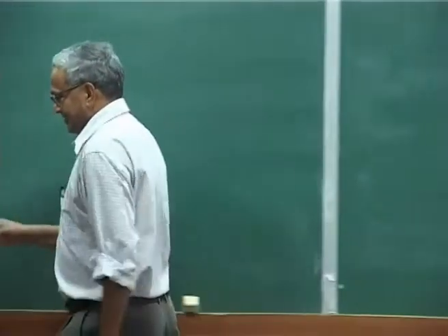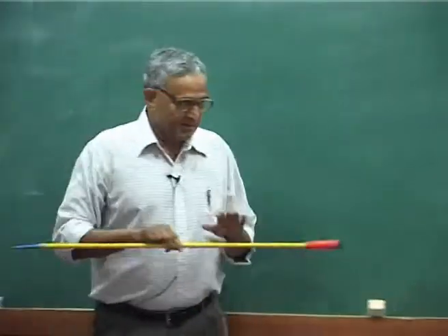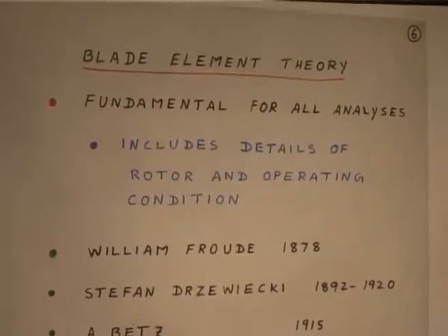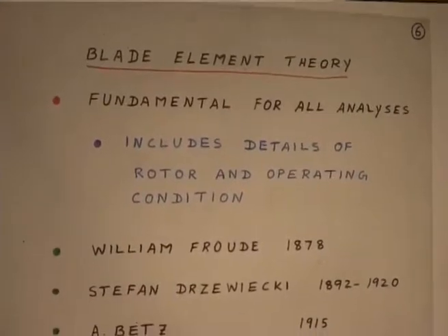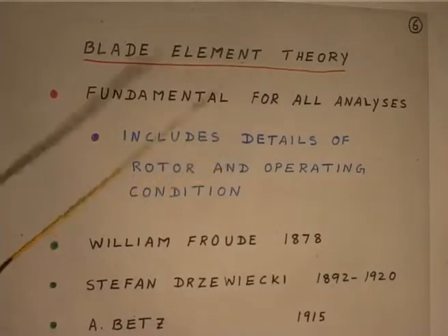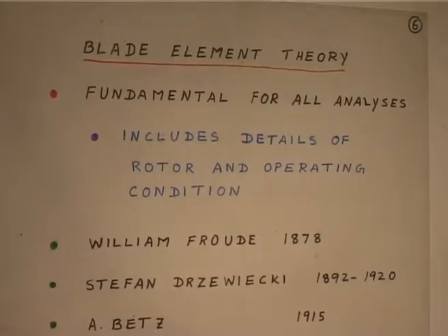Blade element theory, because earlier we related the thrust, the inflow and the power, using only the rotor disc area and induced velocity from momentum theory, but that does not consider any detail. But now we are going to look at the details of the rotor operating condition, everything.